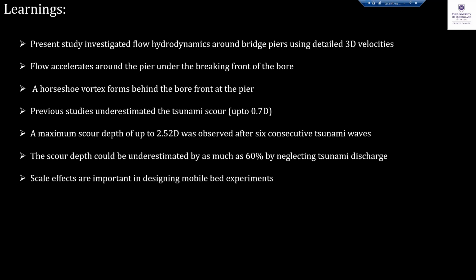And previous studies, as I showed in the last slide, underestimated scour depth by 40% sometimes, or even 60%. So from my study, the key point is that the maximum scour depth due to tsunami can be 2.5 times the diameter of the pier, which is much higher than steady flow scour. And scale effects are definitely important when we want to design experiments, particularly with sediment, and we need to be quite careful about this.